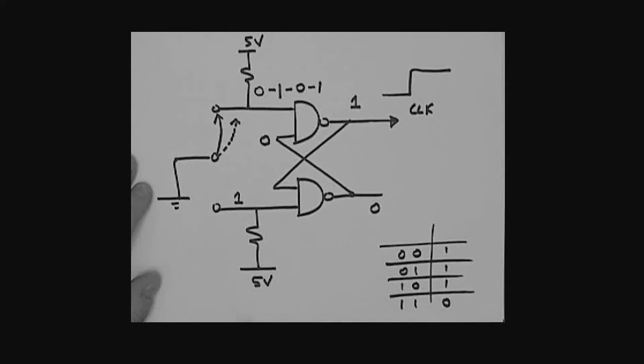Similar reasoning could be applied with the bouncing on this side over here. So this becomes a circuit that you can use to provide a manual clock, so you can really single step, as it were, through your states. So move into a state, check it out, press the button, move into the next state, check it out, and so on.